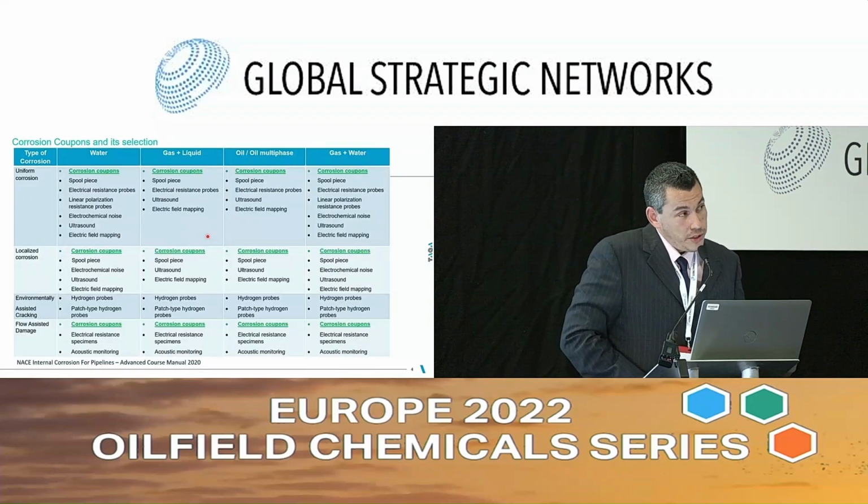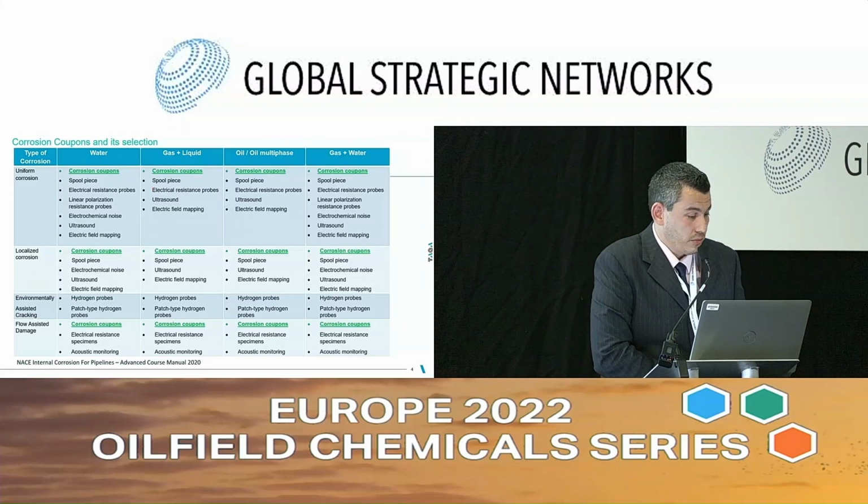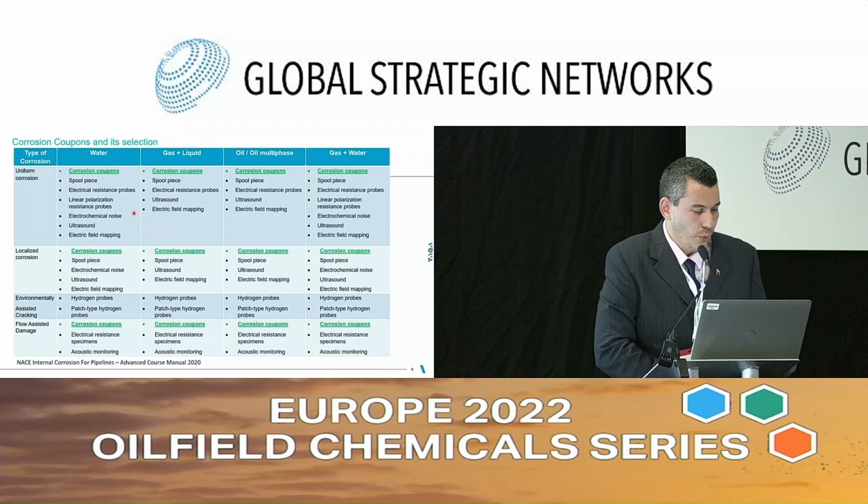So, another way to assess what kind of technique is the most suitable for you guys is what's in your system. Are you handling just water, gas plus liquids, oil or oil multiphase, or gas plus water? Because depending on the media that you are handling and the type of corrosion that you expect, you will be able to match these techniques.